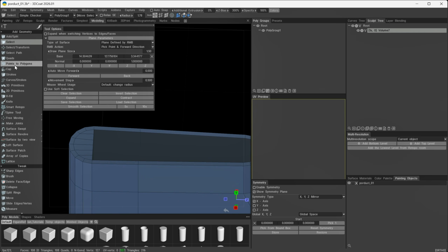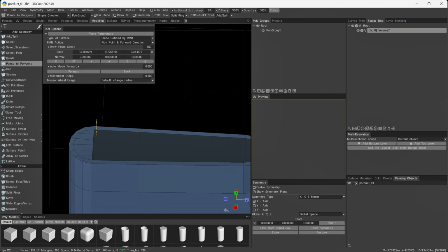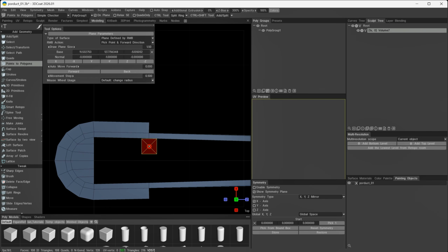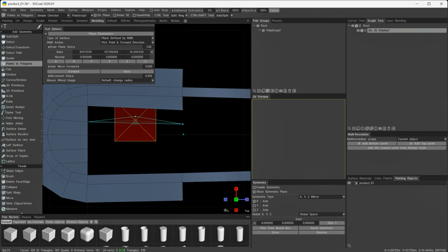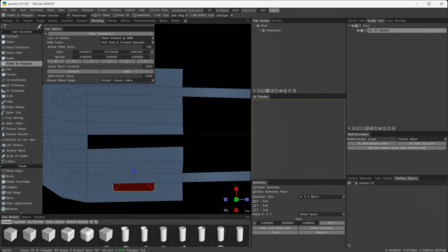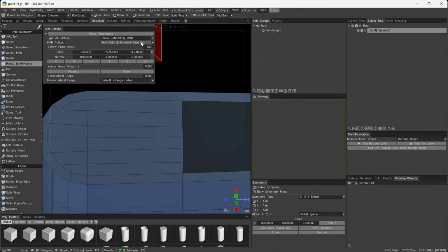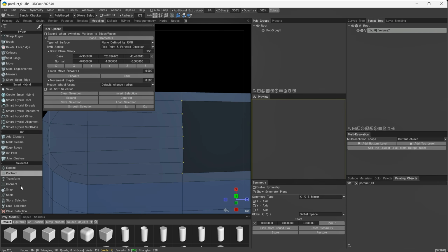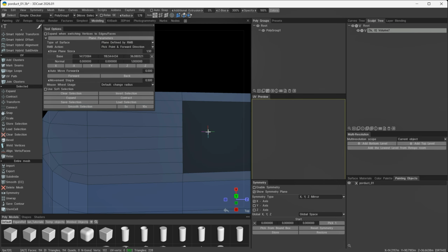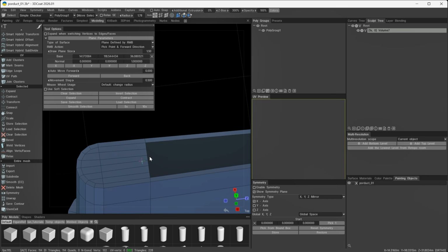We can do the same now for this next row here. Just repeat that process. I'll use the points to polys tool again, and I'll choose this plane here, and I'll put some points in line with these here. Now I can right click again and start to place these polygons. I'll left click, and let's add two more here, left click, left click, left click. And again, select your vertices and we can line those up using the align vertices tool here in the Z axis. Apply, OK, and drop the selection. So that cleans that section up there.